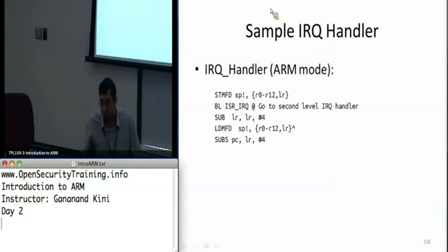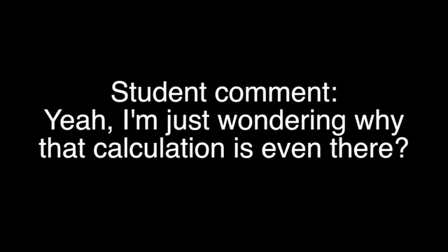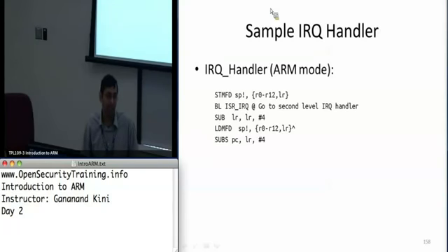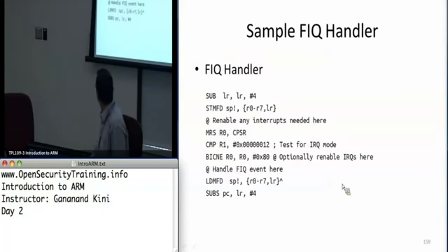Okay, so when you register the link register here, it's going to be taking the link register that you stored on the stack. It's not going to take this calculation into there, yeah, it shouldn't be. Okay. Right. I'm guessing this was for making it re-entrant, so it was an attempt at making it safe in case it got interrupted in the middle. So. All right, so